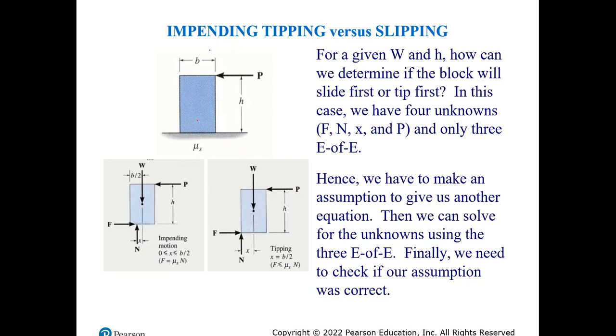With tipping, it's a little different. Let's say at t equals 0, you have the object as you can see here in the picture. And then after the P is applied, you find out that your object is now like this. And we need to look very closely at right here, as the surface in contact is no longer in contact, your only normal force will be applied only at the end, because now you know the location when tipping occurs.